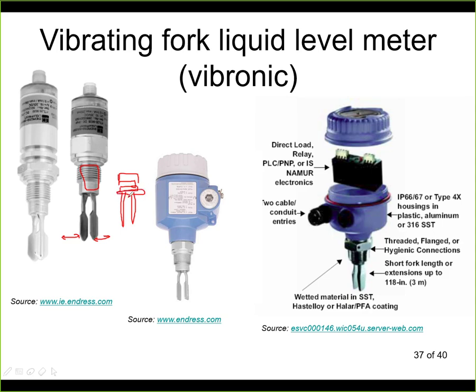You're deforming the diaphragm, and the deformation is created by the piezoelectric crystals, and this makes the vibrations. You measure the vibrations, and this electronic circuit evaluates the amplitude and gives you a signal.